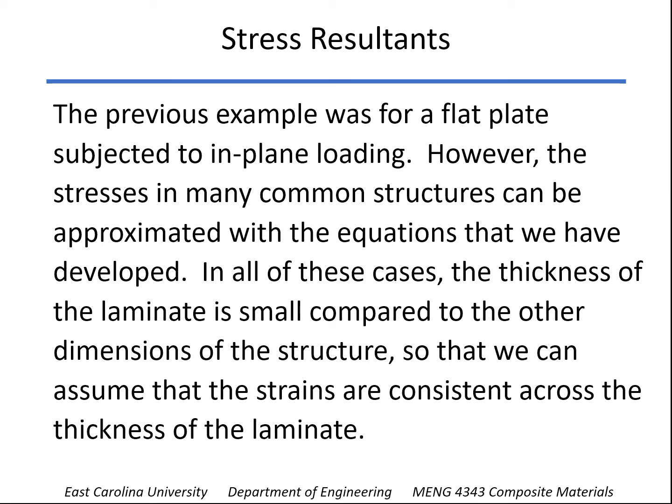So one thing to keep in mind as we start to look at these is that our assumption here is that in all these cases the thickness of the laminate is small compared to the other dimensions of the structure. That means that the strains in the laminate are going to be the same throughout the thickness of the laminate. So if we have bending, that's not going to apply here.